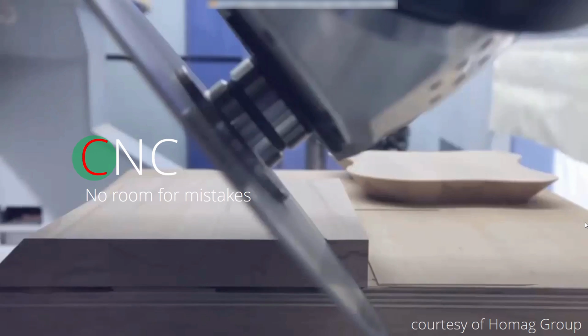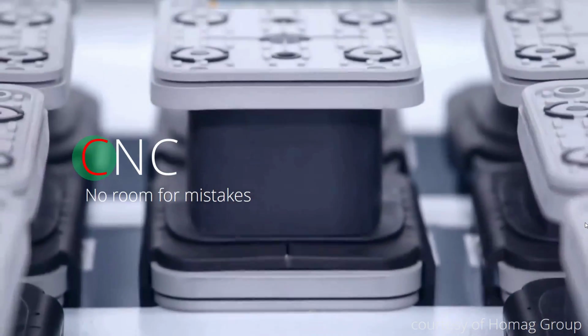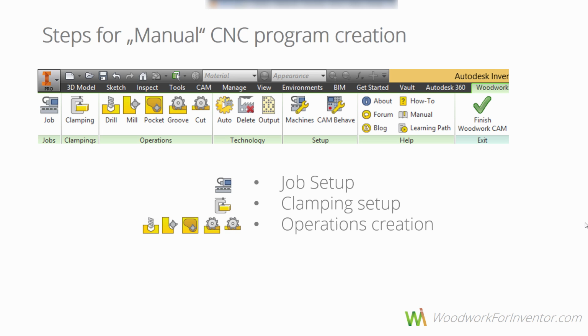Let's see how we can deal with the CNC, one of the last steps in the preparation for manufacturing. There are two ways of doing things in Woodwork. If there is quite complex geometry, or some technological nuances you need to consider, you can use manual CNC program generation, which means that you can generate a job setup, set the clamping, make operations and output the CNC program in a manual way.